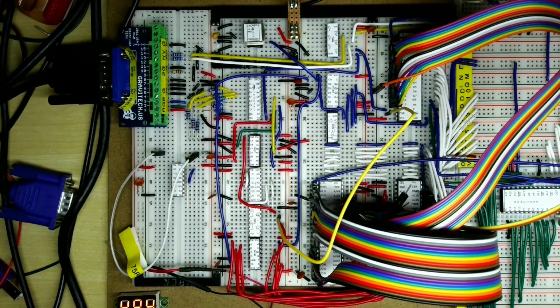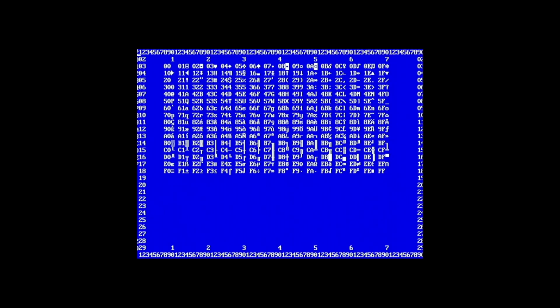And if we now just go to our VGA capture, you can see there's a flashing cursor in the bottom left hand corner, but you can see it's maybe a little small to see, but you can see that the cursor isn't quite in the right place. It's sort of coming out sort of halfway under the number 1 there. So when we have finished adjusting our various other timing signals, hopefully we should be able to see what's going on there.